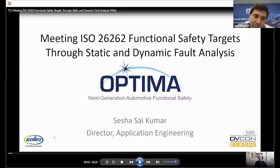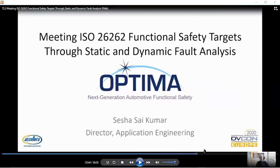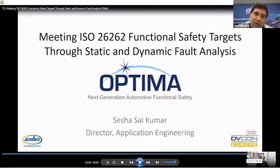The demo that hopefully we'll show in a second is for the software solution. The main concept here is that we do fault simulation on many flops to calculate the AVF, so that you can do selective hardening to decide which flops need hardening and which don't.